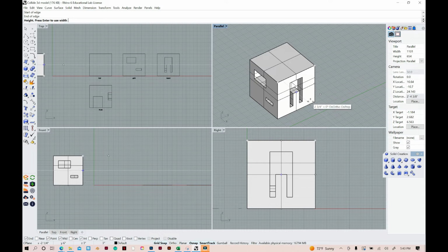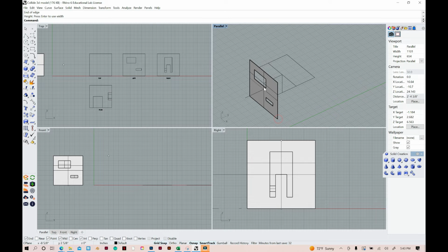So we're starting off with the right side, but I actually want the left. I want to go in order so that I'm not confusing myself. So before I click, I'll press escape and do that command all over again. Clipping plane, vertical, and I want it on this side. Click, highlight the top to identify the side, and then cover the side.